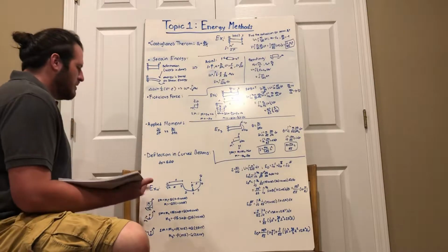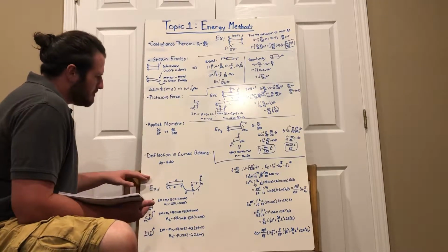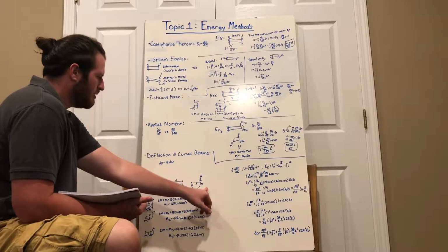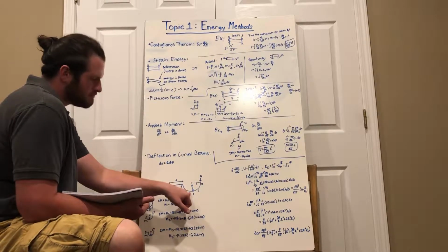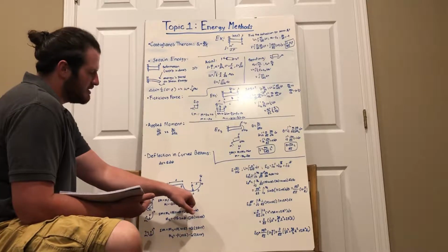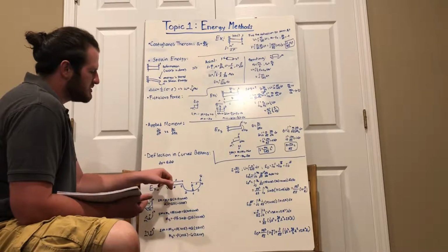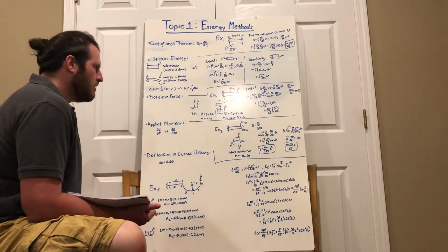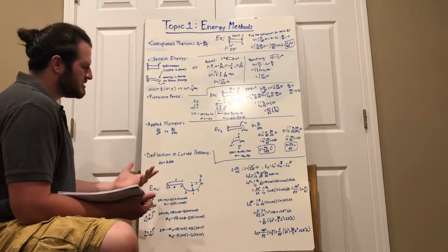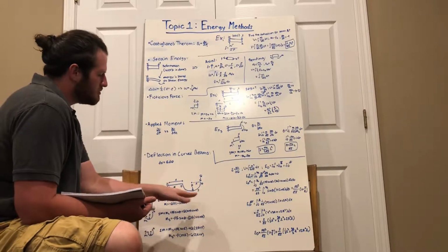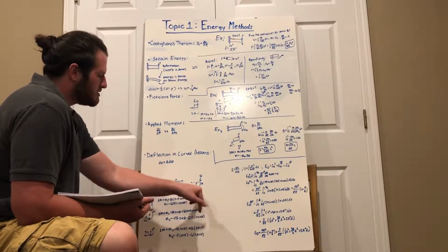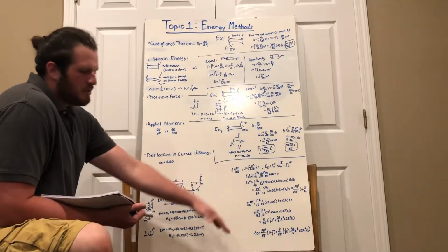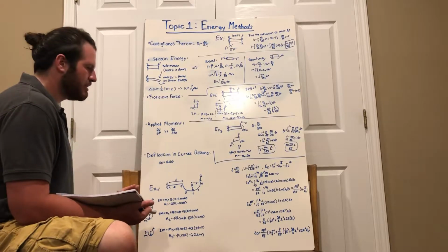So let's look at this example. We want to find our deformation at this point D, given that force P is applied at C, and other parameters L and the radius of the circle R. What do we have to do? Well, first, like before, let's break it up into different parts. Let's start from right to left again and label our parts 1, 2, and 3. So we're going to have 3 parts, 3 moment equations, and 3 things to add up later on.